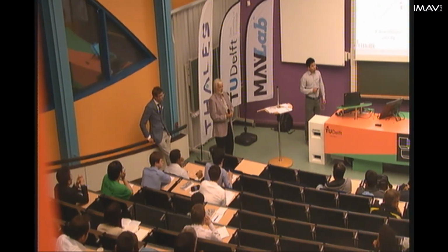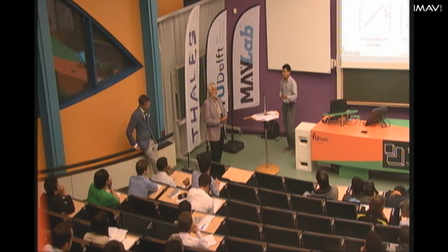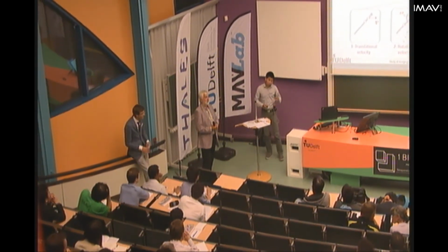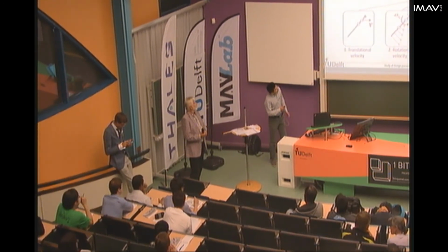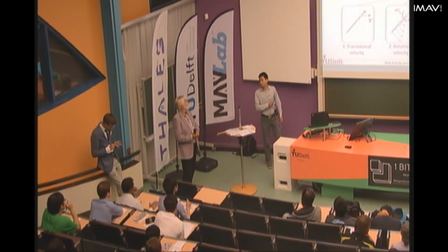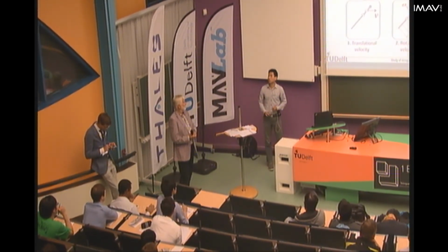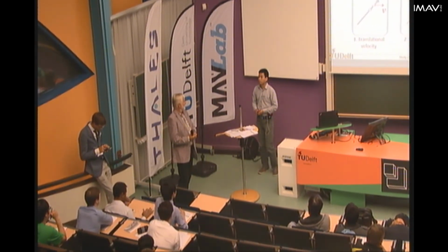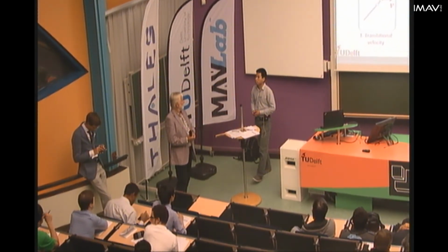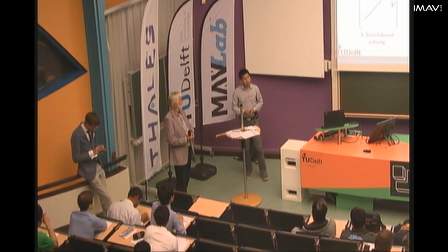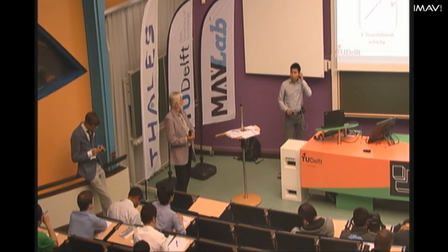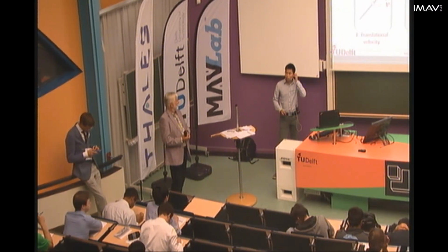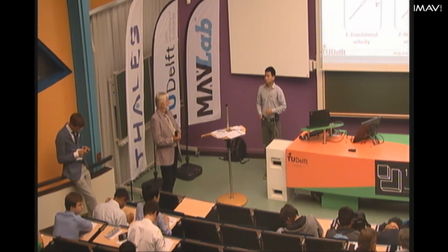Well, first, both the lift and, I would say, the aerodynamic forces are first calculated in the rotating frame, and then transformed to the inertial frame. For CL and CD of the wing section, you have to calculate the force on the wing section, and then you integrate on the wing to get the lift, right?